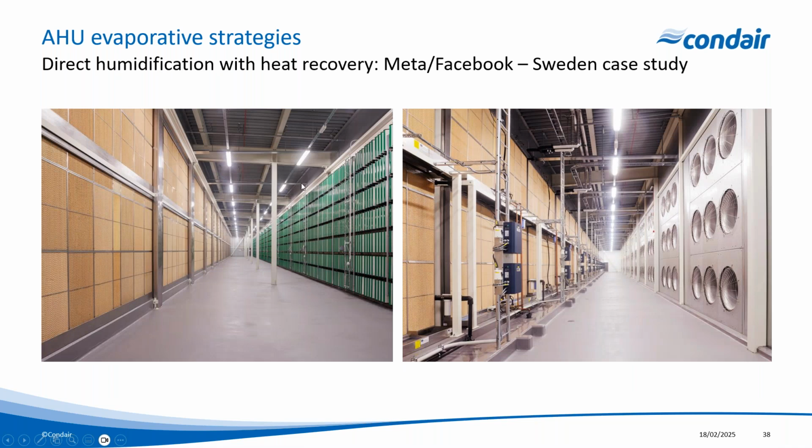Here you can see some actual photos of the evaporative systems. On the left side in both images, you can see the evaporative media. In the first image, we've got the filter section with the green filters. And then in the second image, we've got the fans on the opposite side of the humidifiers. In this case, the humidifiers were actually full walls of evaporative media, double stacked, spanning across the entire plenum.